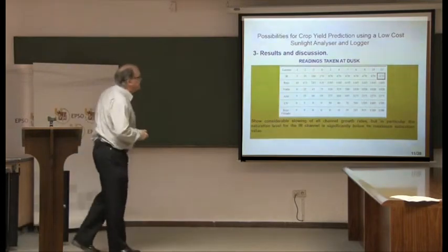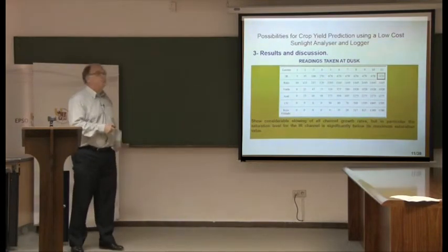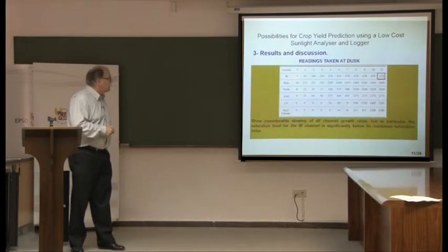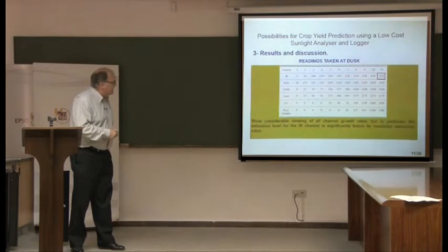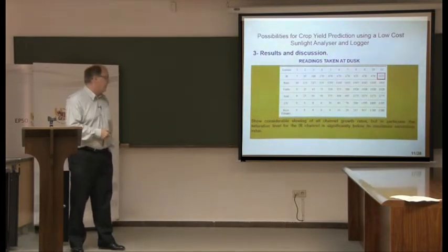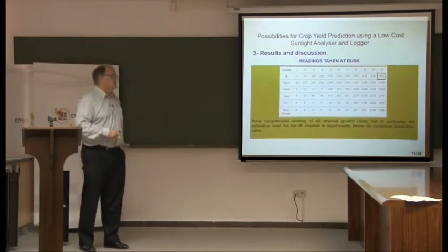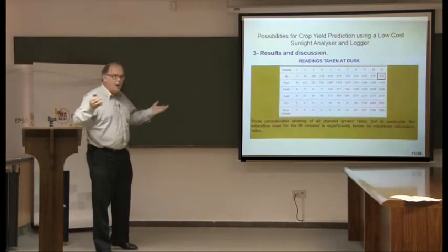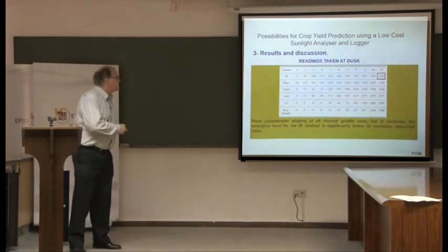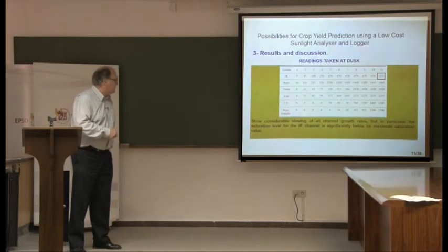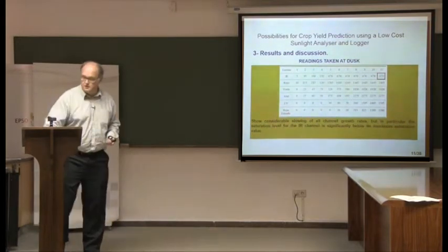By contrast, if we look at these readings taken at dusk, when obviously the light levels are much lower, you can now see that our infrared readings grow quite slowly and then saturate at a much lower level than they did on the previous slide. And what we basically said was, how can we take a subset of these values and use this to say what the current lighting conditions are? So instead of looking at all 11 of these, we look at the 1st, the 4th, the 7th and the 11th, and we don't even bother with the red filtered light at all.